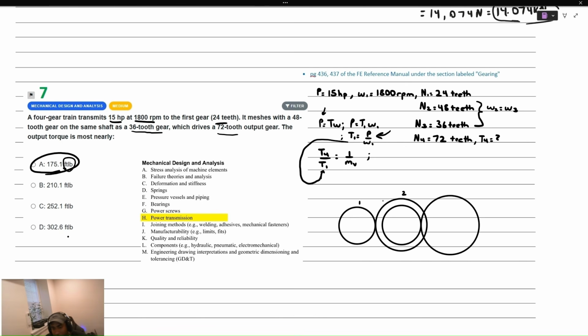The average radial location of that line is used to determine the pitch radius, and double the pitch radius, you get the pitch diameter. And we can use that diameter to draw circles, right? And that's what we're drawing here. So it represents the average contact point, and the pitch radius, the pitch diameter, these are used in all of our angular speed, our torque calculations, right? So it's a super important concept here.